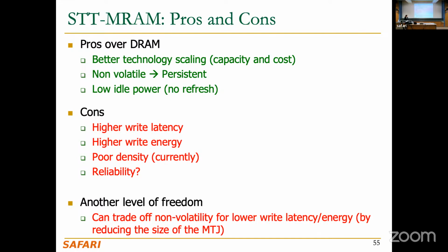In these NVM technologies, we can provide another degree of freedom: we can make a trade-off between non-volatility and lower write energy by reducing the size of the MTJ cell.